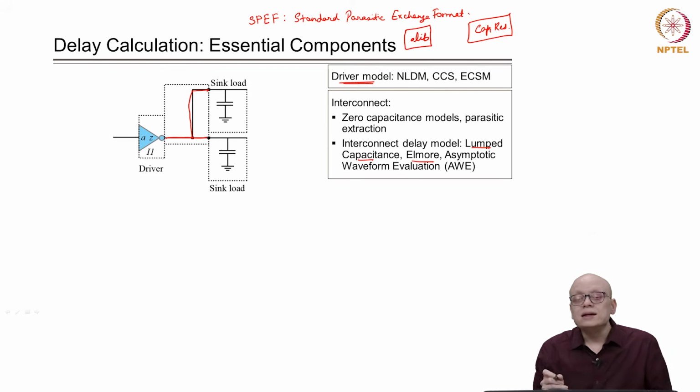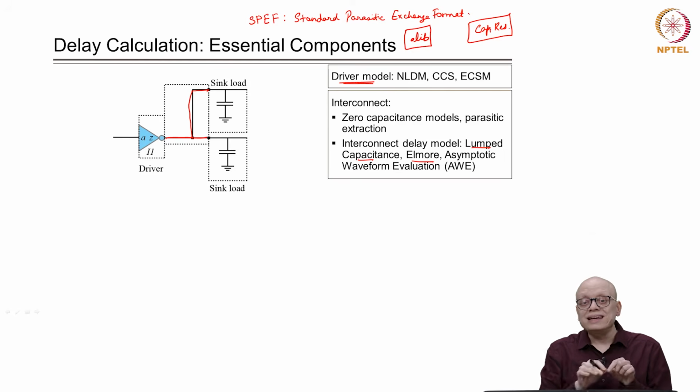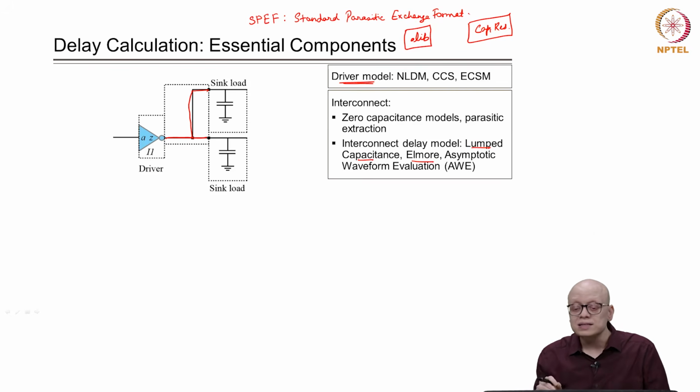This contains the resistances and capacitances of the interconnects, and using this SPEF file, the tool can use various interconnect delay models such as the lumped model, Elmore model and so on, and then compute the delay associated with the interconnect.